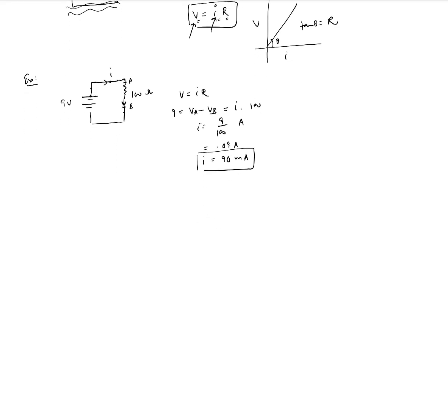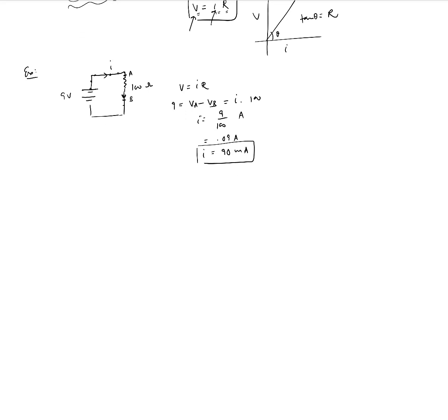So Ohm's law can be applied to different kinds of circuits. We'll discuss two kinds of circuits over here. One is the series circuit. As the name implies, in a series circuit, you have the resistances or the loads basically applied in series. So for example, you could have 3 resistors, let's call them R1, R2, and R3, connected in series end to end, and there is a single battery, applying a voltage V, could be 6 volt, 9 volt, 12 volt, doesn't really matter. But we know what this voltage difference is, as well as we know what these resistance values are.